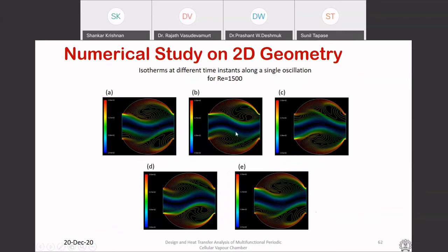So in the next time instant, this recirculating zone has penetrated into the core flow, while the top now starts to. So the flow is oscillating back and forth, the main core flow that is shown, that is sort of blue in color here. So it is changing shape, you can see that. Then the top starts to interact with the core flow and it ejects its vortex. Then the bottom again, the same type of situation arises. And finally, this is going back to the original cycle here. So this is the type of motion that happens in these 3D unsteady flows.